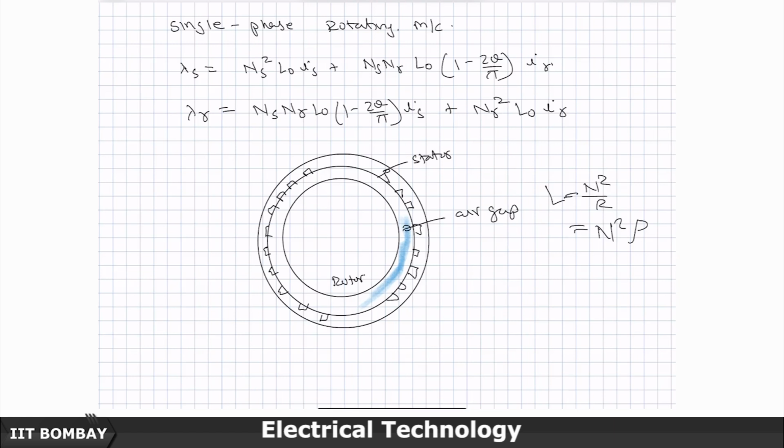I cut it like this, and let us say the dots are here, that means current is coming out of the windings here, and current is going inside from top to down here. So, current comes out, overhang, there is no magnetic flux there, just a connector, then goes down, then from below connects back, like this, like this, it is going,